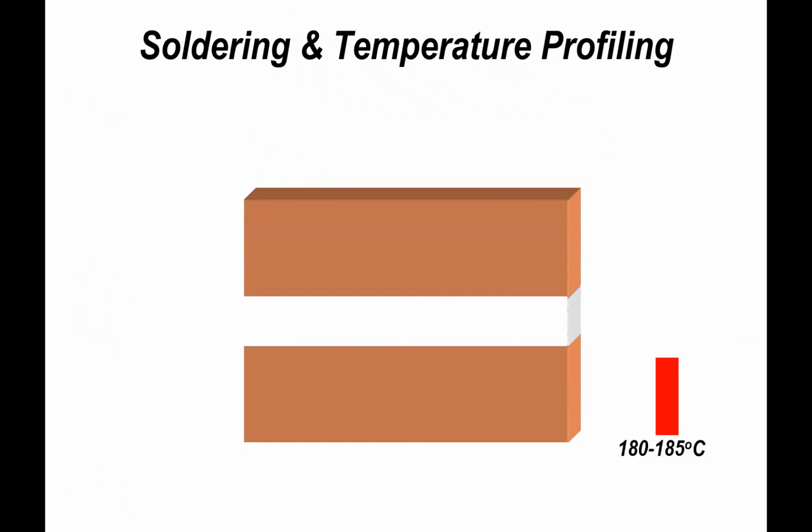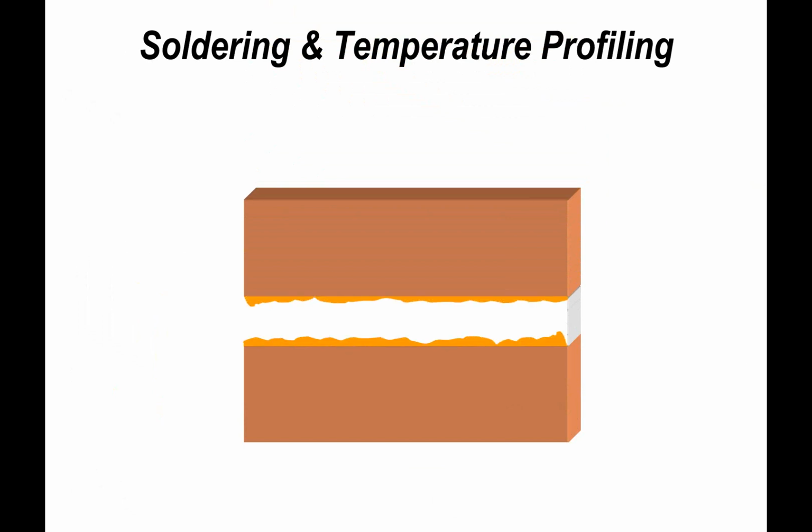But slowly, when we get up to reflow temperature, if it's tin lead or lead free, the solder will become a liquid, and in that liquid phase we'll start to form a solder joint, which will obviously incorporate intermetallics across the surface. Those intermetallics will be different depending on the materials you're joining, but if we're just talking about solder, it's copper and tin.